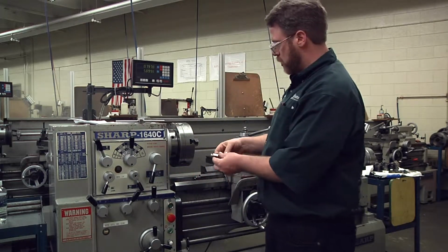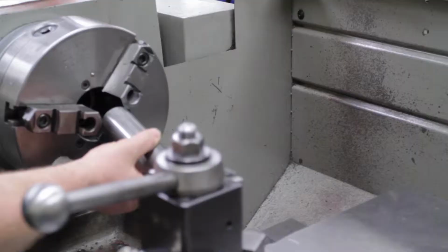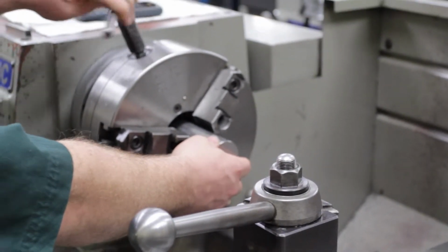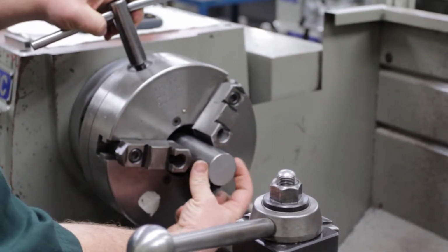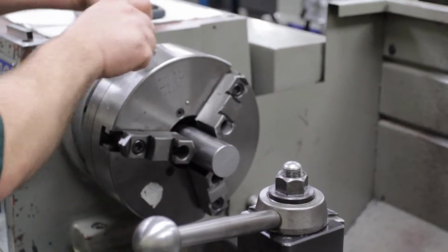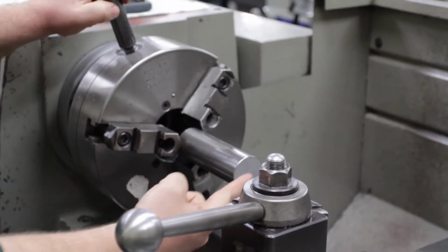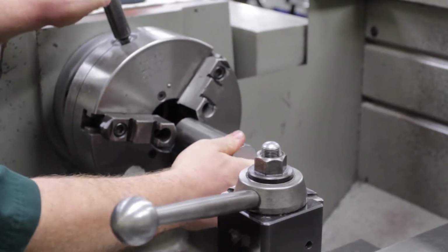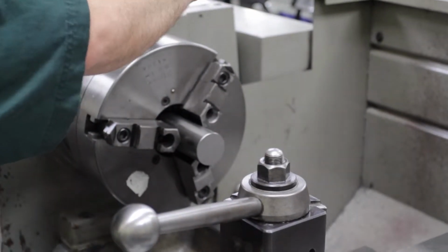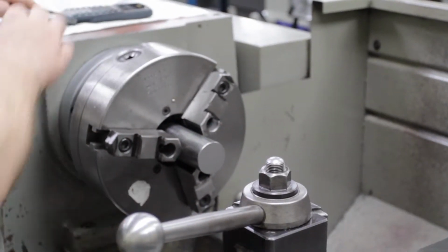The next thing is to get the workpiece in the machine. We're going to use a 3-jaw chuck here for today's demonstration. So we're going to put it in. Leave it stick out about the diameter. If it's 1 3/4 diameter, leave it stick out about 1 3/4 inches. The reason is you don't want to have it sticking out this far. When we go to cut the end of the part, you're going to have a lot of deflection on the part. So to make it a nice, strong, sturdy setup, only leave about the diameter of it stick out.